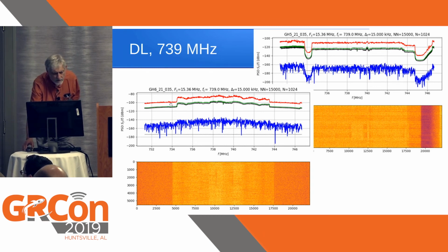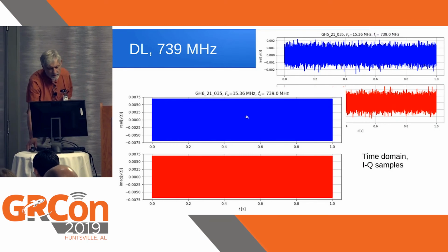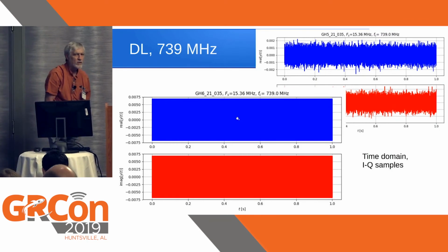You can see that the noise floor, which is somewhere out here, is way too high. It's about -110 dB, whereas here in this case it's -120 or even less than that. And so once we looked at this in the time domain, then we see this picture here. So what you see on the left here is basically just overdriven.